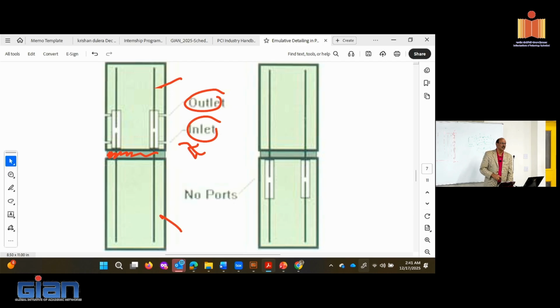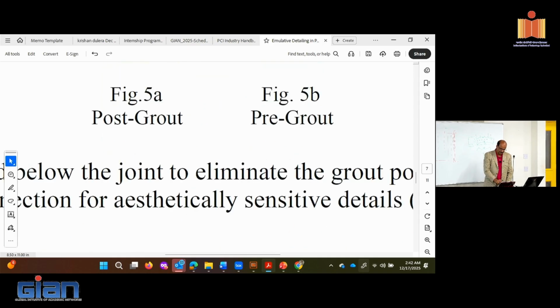Now, after your visit, we propose a system with a positioner. So that will take the construction load. We are going to do the grouting at a later stage. We just propose, but erection engineers are frightened. Yeah, so that's an advantage, but you also have an advantage that some of the weight settlement, those things, take place before you start grouting. Otherwise, you are unnecessarily putting loads into the system.